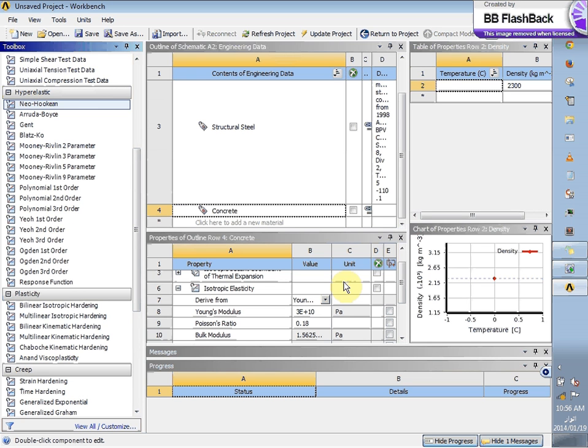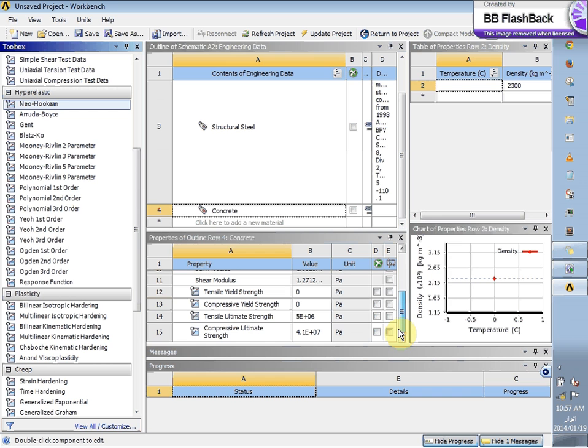Like steel in molten state behaves differently. Steel, when it is yielding, in the necking zone, it is a new steel. It is not mild steel anymore. It's a different type of steel. That is why it is yielding there. Other steel is still steel, structural steel. So if you want to see that necking behavior, you have to put new properties of steel there, which is a new steel. So you can add those behaviors from here. This is how you can change the material properties.